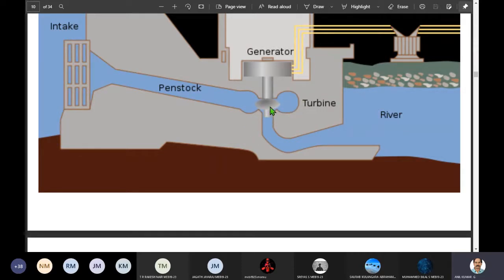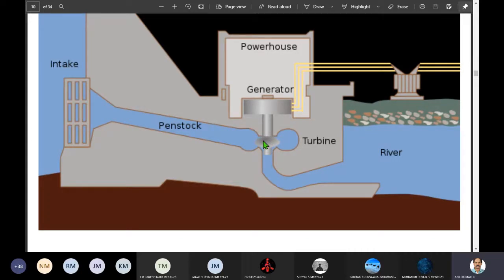And in simple turbines or small scale turbines, you can think of a shaft which is horizontal and the turbine in a vertical plane. But in very huge turbines, this is the configuration in which the turbine is oriented or installed. So we have the turbine here. See, this is the turbine runner. It will rotate here, and this is the shaft. And above the turbine, on the same shaft, you have the generator, and that is a powerhouse.